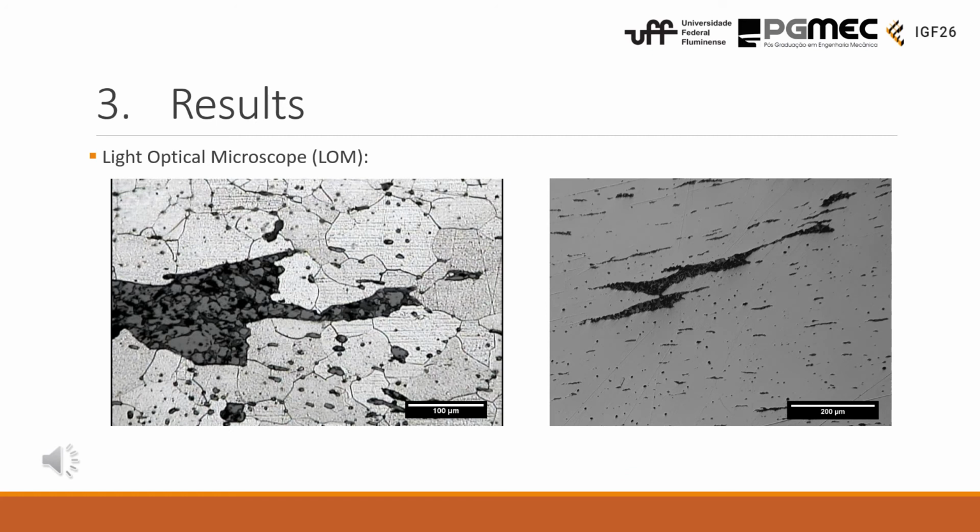In accordance with the chemical composition and thermodynamic analysis, the material presents a high amount of inclusions and also big slag inclusions, as we can see on both images. And this is due to the manufacture process of this ancient material called Pardal iron that was mainly manual, so the workers weren't able to remove all the slags, resulting in this type of microstructure.